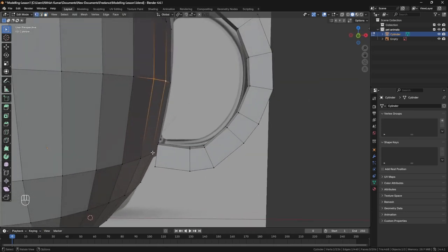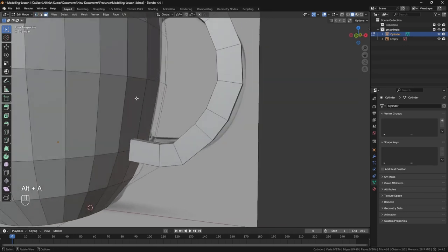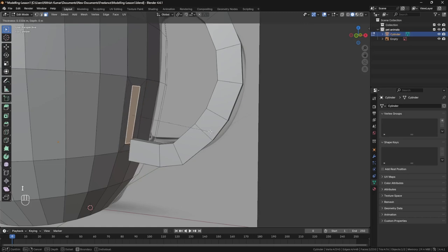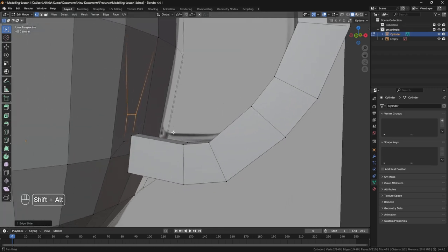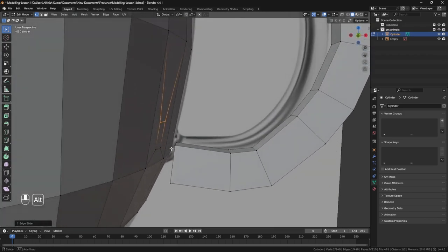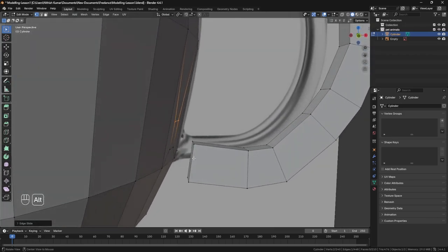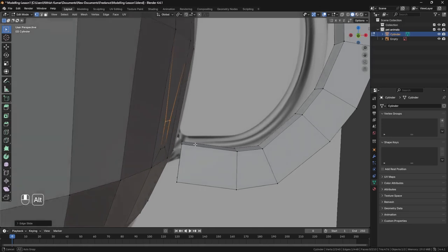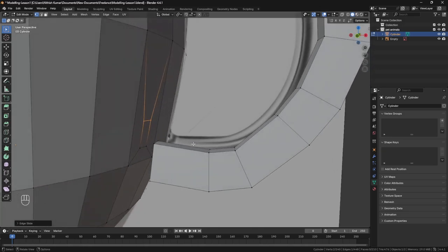Select whichever faces, but it's best we go to face selection, select the face, press I again, shrink it down, select this, bring it down by pressing double tap G, and then do it like this. But from here we can see this size is different and this size is different. So how do we solve this?